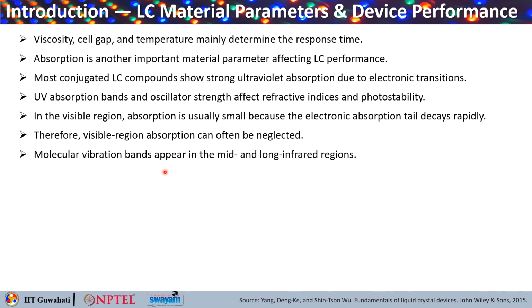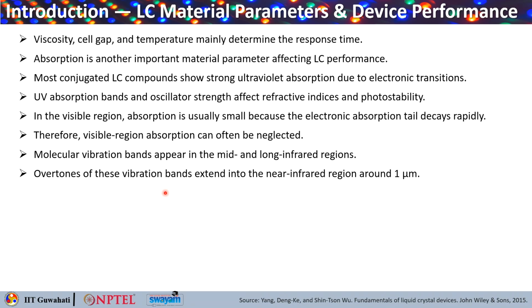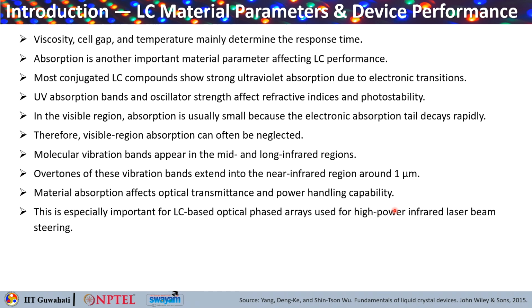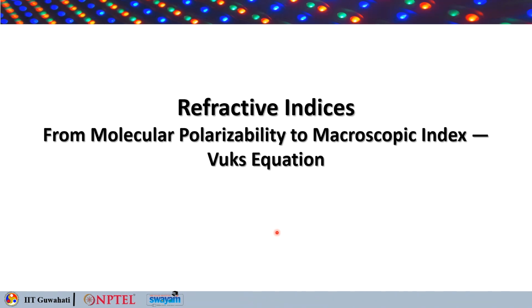Molecular vibration bands appear in the mid and long infrared range, and overtones of these vibration bands can extend into the infrared region around 1 micrometer. So the material absorption affects optical transmittance and power handling capability. This is especially important for liquid crystal based optical phased arrays used for high power infrared laser beam steering. So these are the important liquid crystal material parameters and the device performance that is obtained.